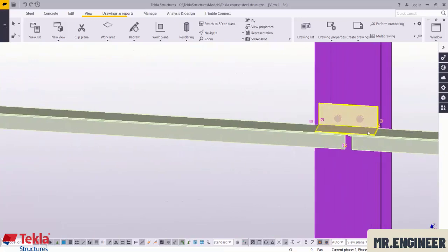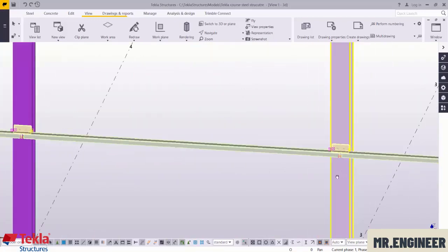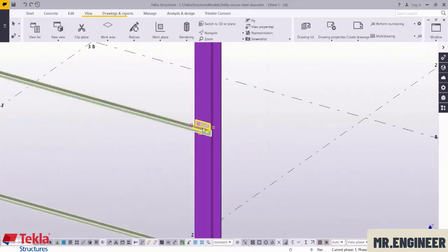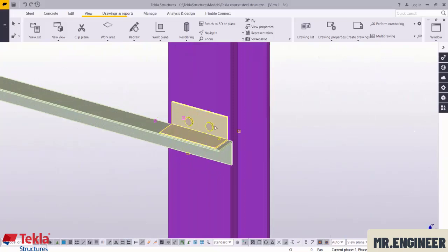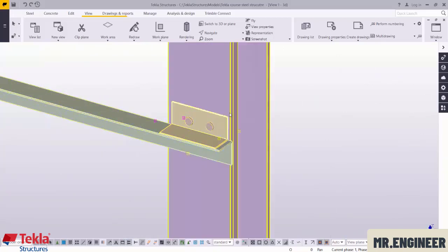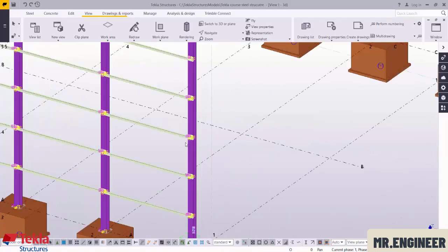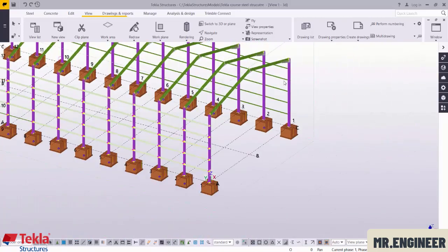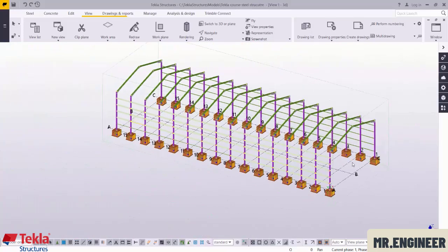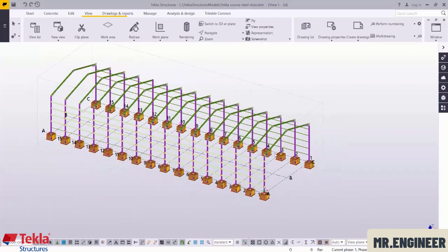We need some distance here. Then we draw manually a connection between this rails. Okay, the rails here we have weld between the connection and the rails. Then we put stud connection between the column and the rails. Then we do the copy to the other side and to the other grid like this. Thank you for listening. We will continue on the next lecture.